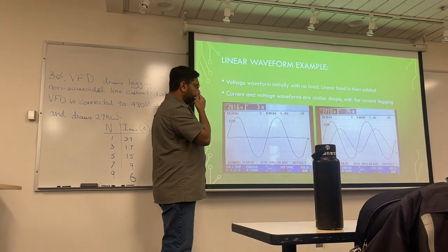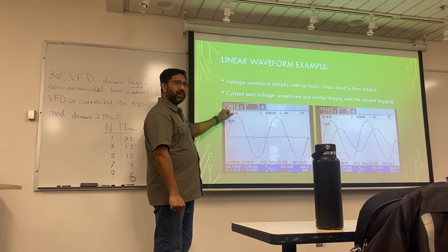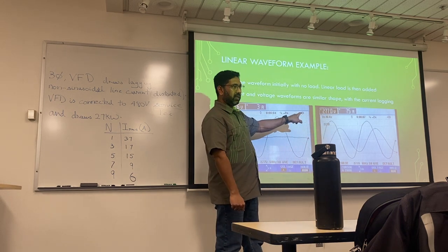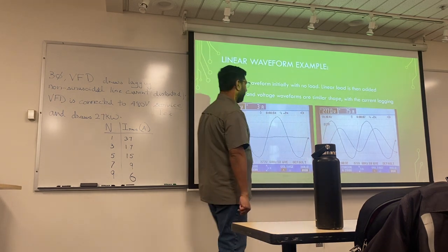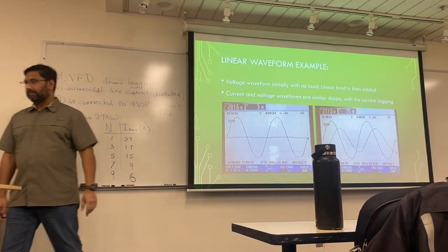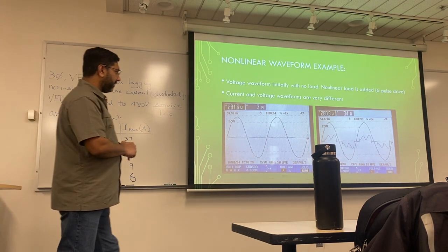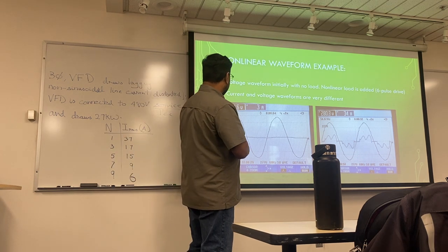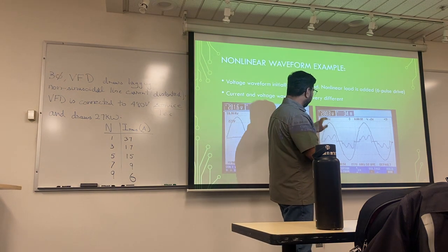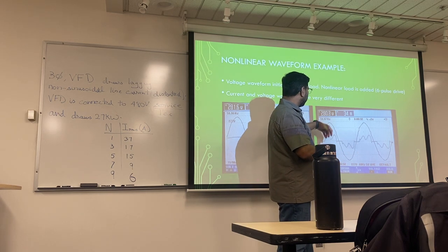You may or may not notice this. We do a trick where we supply a bit higher, so that when you put a load, you get your 277 for a linear load. In fact, it's 277.2. We change this throughout the day depending on what's happening. And this is literally from a customer. Our ask was to supply 277, and once we were supplying 277, current distortion started to take place, and that messes up our voltage distortion.